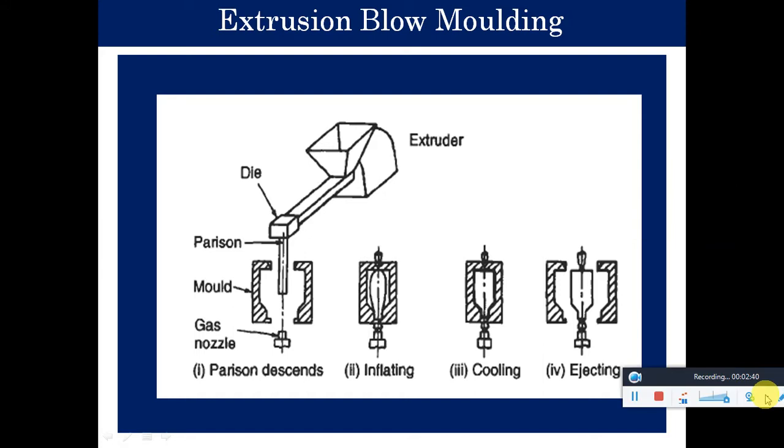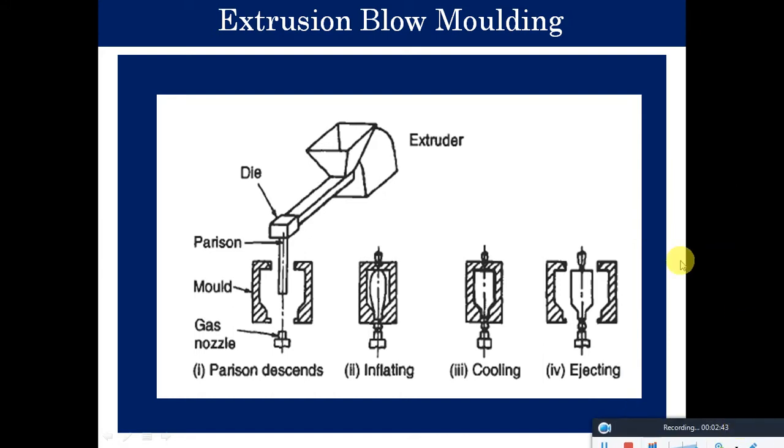First, to explain extrusion blow molding, you can see this schematic representation. From this we can easily understand how extrusion blow molding is done to make a product. We have an extruder which is attached with a die at its end. This die decides the actual size of the Parison. Parison is nothing but a molten semi-solid gel-like form of the raw material. The die has those geometrical criteria, and according to that the Parison comes extruded from this extruder.